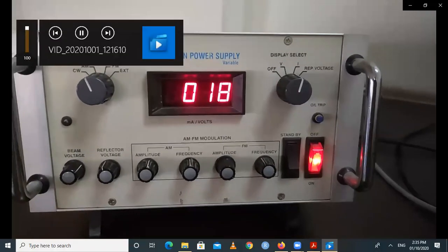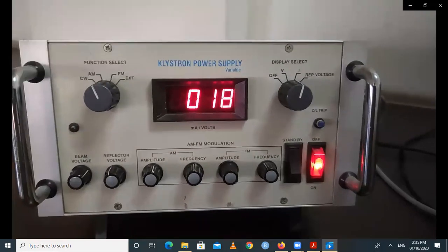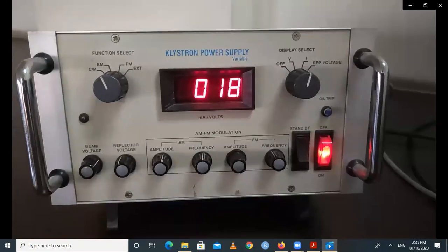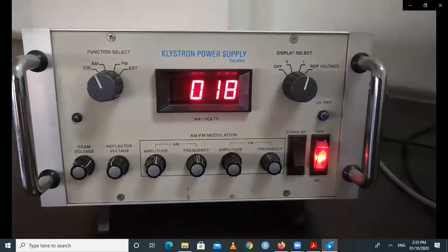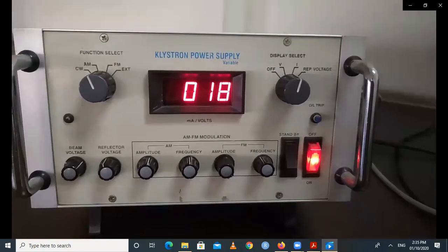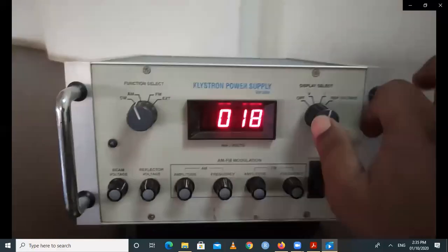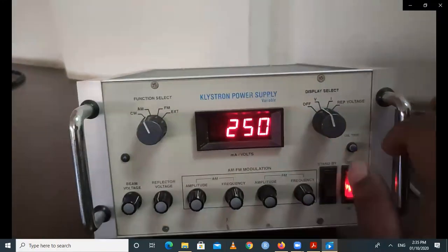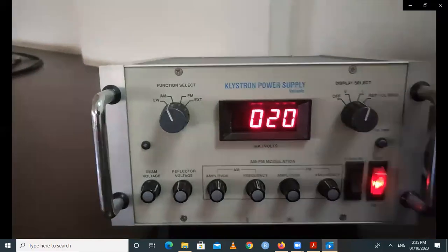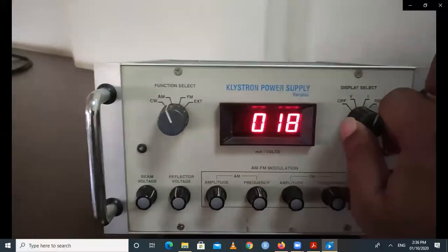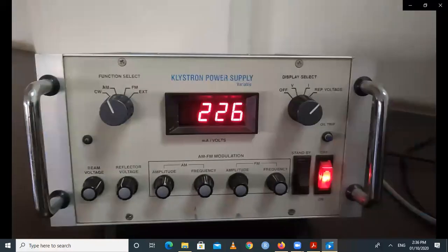You have to wait some time for that particular filament to cool, and after that you have to start again. So the point is that this beam current should not be more than 18 milliampere. So what we do up till now, we set this beam voltage to 250 volt, then we check the beam current is not greater than 25 milliampere, and then finally we go for the repeller voltage, REP,